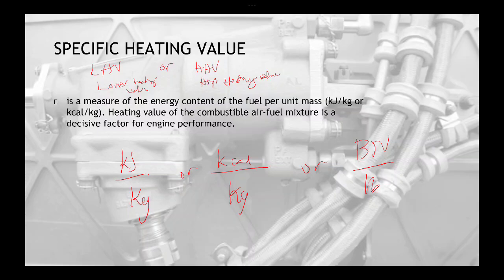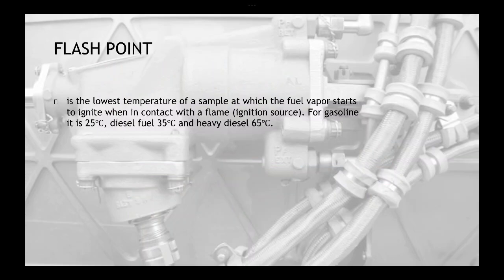Furthermore, the heating value of the combustible air-fuel mixture is a decisive factor for engine performance, and that is specific heating value. Now let's move on with the flash point. Flash point is the lowest temperature of a sample at which the fuel vapor starts to ignite when in contact with a flame. So that's basically the interpretation of it. That's the lowest temperature at which your liquid fuel, when in contact with flame, will ignite.